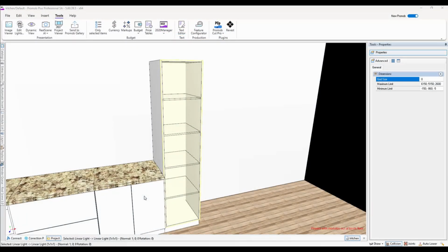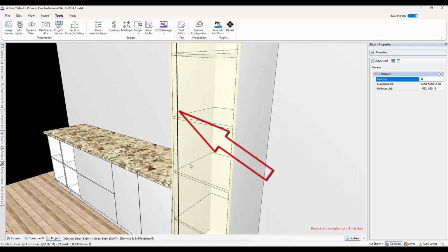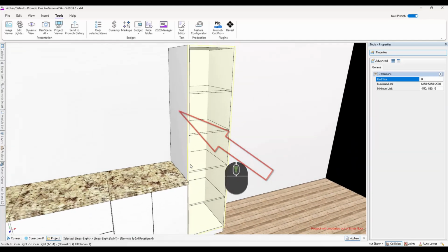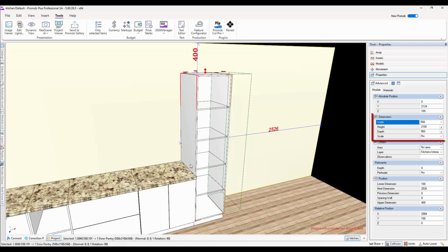Okay, today we're going to show you how to put a strip light vertical into a cabinet, similar to what we have over here. We've got a strip light there. I'm going to show you an easy way to do it. So the first thing to do is obviously click on the cabinet. We need to know the size of the cabinet. It's 2.1 and we know that it's sitting 100mm on the kick plate.